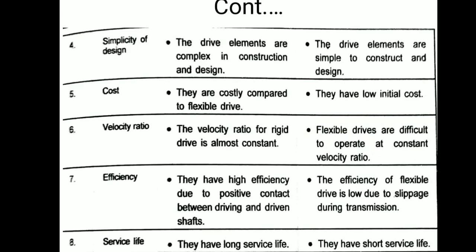Now service life. Of course, gear drive is having long life because a number of teeth are available there. But in case of the belt drive, the load comes on a particular area of the belt continuously after some interval. So there might be chances of breakage of the belt. So life is short.